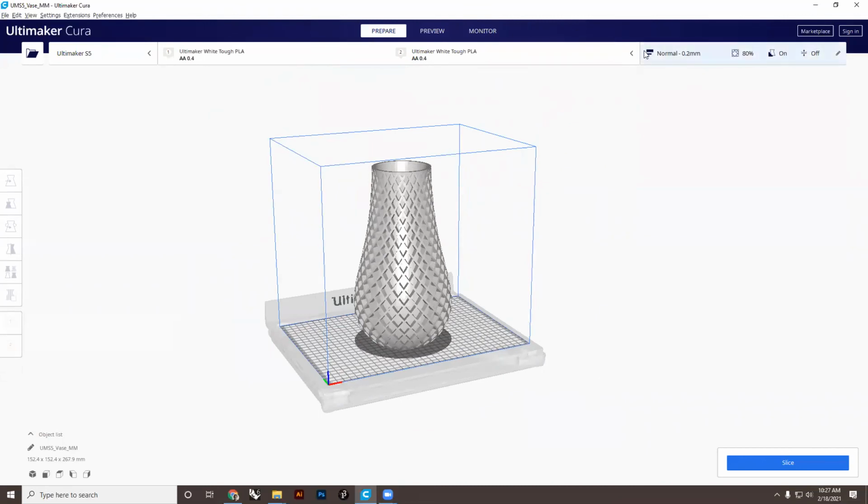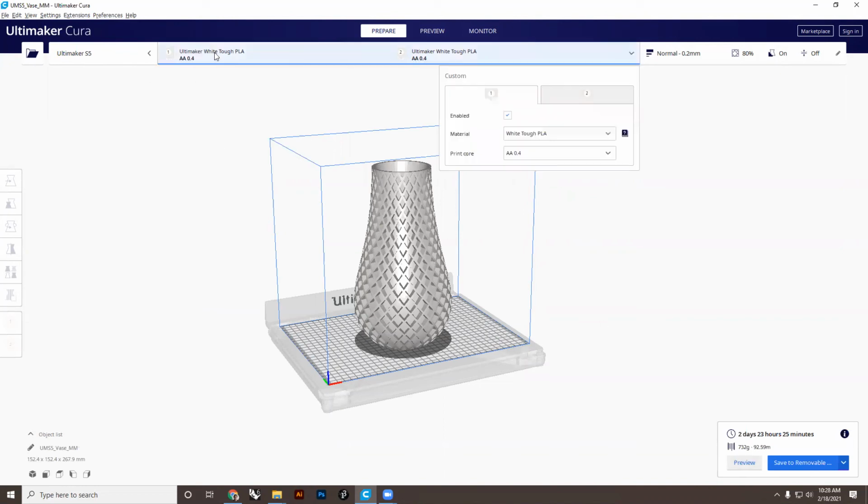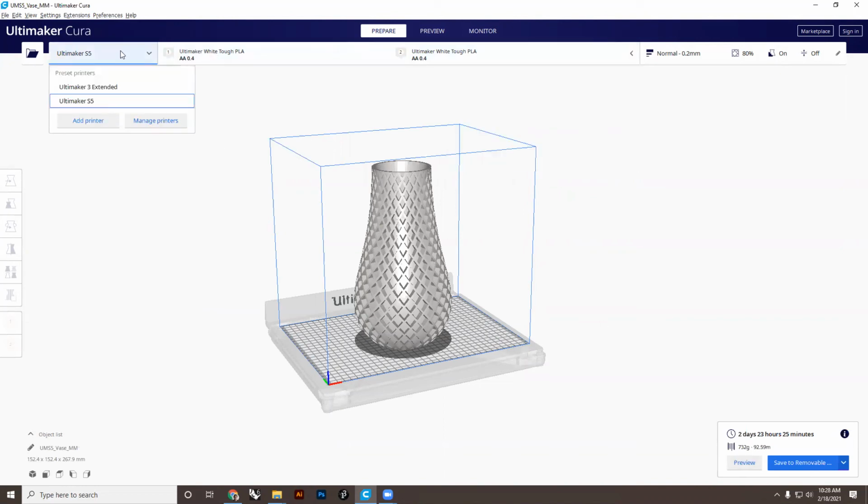Once you have all of that set, you can go through and slice the model. This is the part that's essentially creating the G code that's going to tell the printer where it needs to move and how it needs to move. The reason we don't have you go through all of the settings and all of that setup and slice it and submit the G code directly to us is because we, again, have a little bit different settings, and it'll be a lot of work for every student to learn all the different settings that we use and how to adjust that. But also, if there's any issues between the different types of material that you have set, or if you have a different machine set up, it won't let you change any of that. The G code will package itself and say, this is the specific machine that I'm meant to print on.